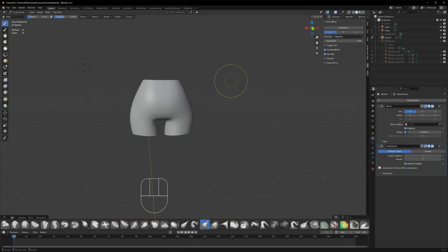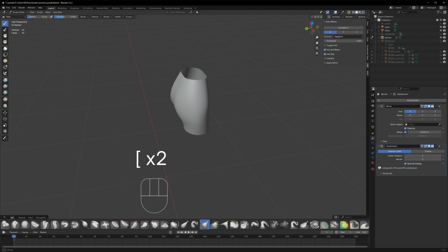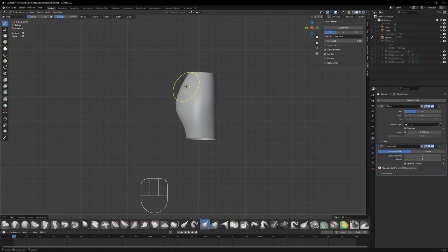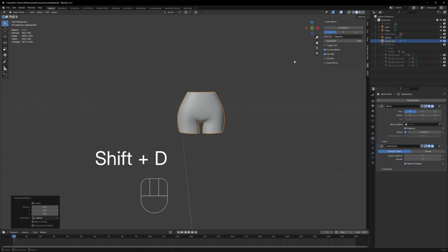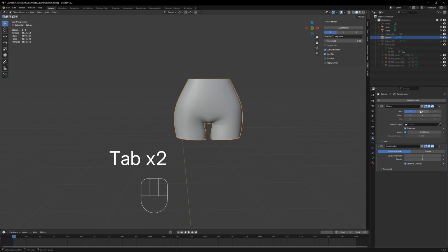Now, if you've been following along, I highly recommend that before you apply modifiers, create a backup save or duplicate your mesh as a backup. Especially if you're planning to wait for the rest of the body tutorial, which will drop in a few days. I usually model the whole body before I apply subdiv, but today this is just an example of how I reverse engineer, so I'm only focusing on one part. All that being said, I'll now apply the mirror and subdiv modifiers.